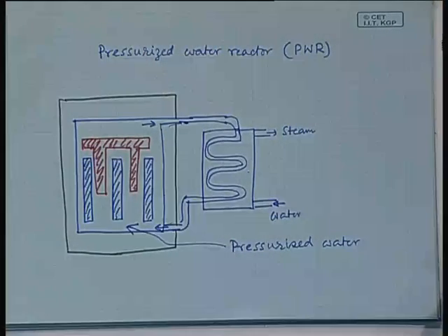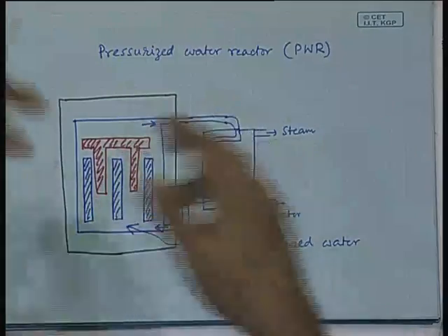Okay. So, what happens is that while it uses the available amount of uranium-235 and converts it into energy, it also generates more fuel, and in order for that process to work fast, the neutrons have to go fast and hit the thorium or uranium-238 nuclei, because here the objective is different. Here the objective is not to fission the uranium-235, rather to convert the uranium-238 into 239. So, you do not use a moderator.